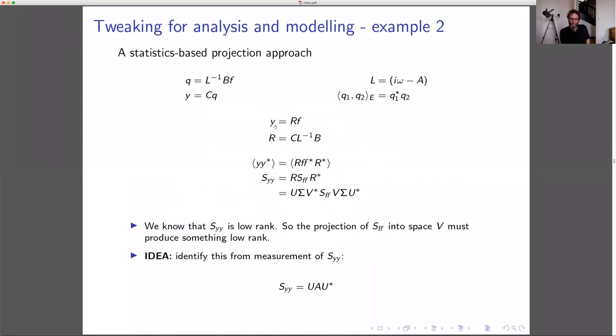This is the resolvent system written, so Navier-Stokes written in input-output form. And here already I'm talking about an acoustic output. We're talking about the jet again, and so Y has been localized in the acoustic region. So the resolvent operator I'm talking about here already has these C and B matrices that focus on the relationship between the jet and the sound field.